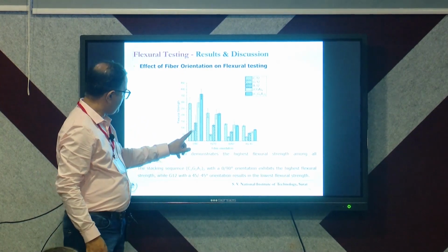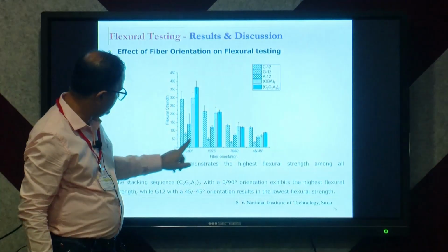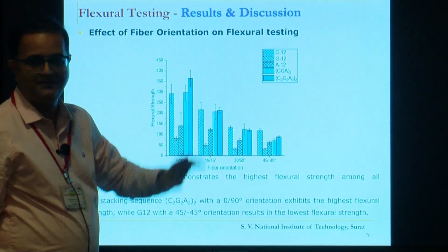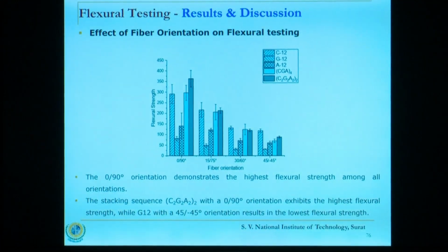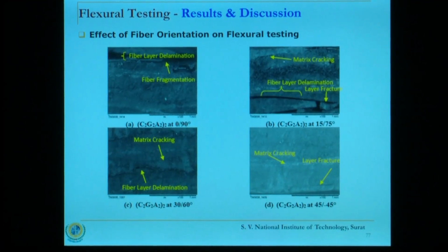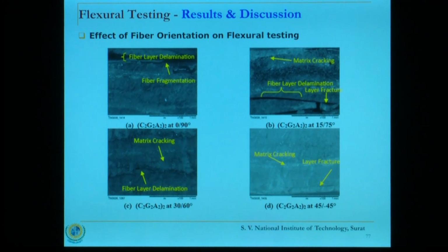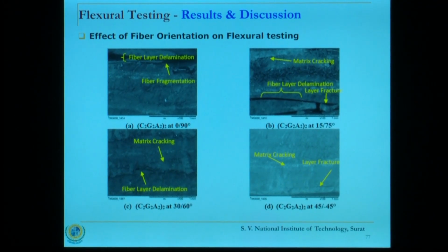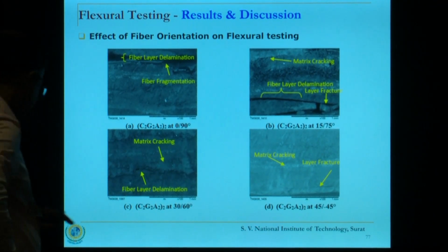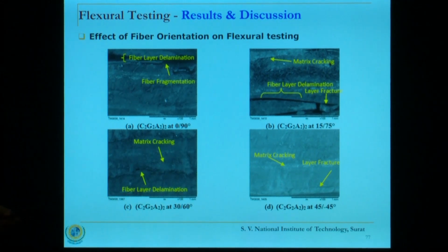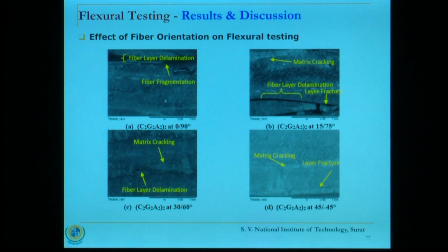Glass fiber always remains at the lesser side, the second one, glass fiber. See, this is how the delamination goes. This is at 100x. So the matrix breaks, right? There is cracking in the resin matrix, and then the second part is the delamination of the fibers.